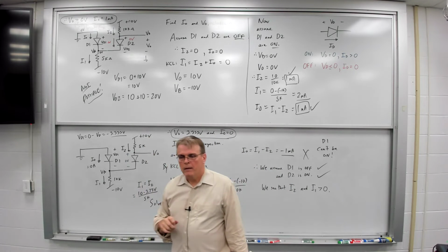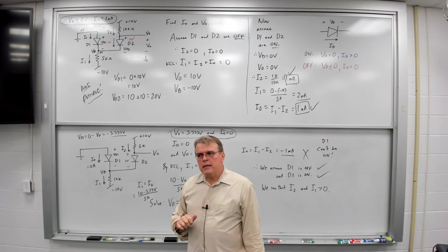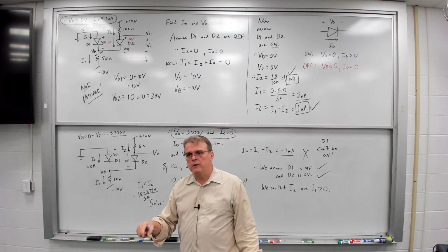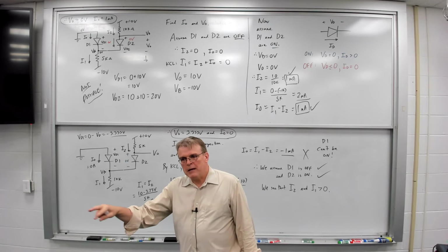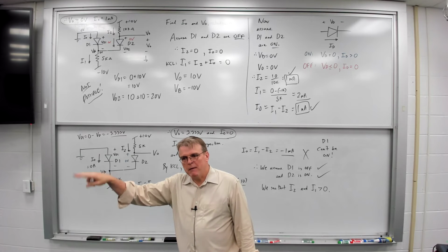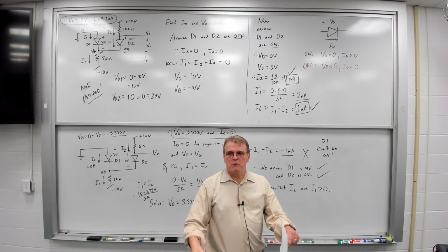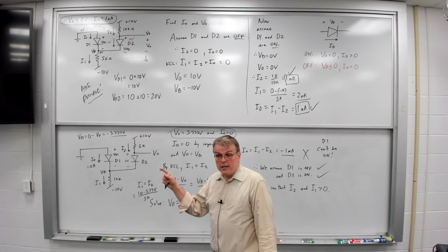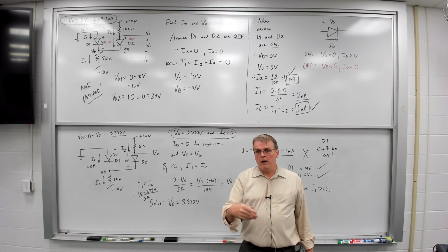Yeah. But isn't that property unique to logic circuits? Well, it's not unique to logic circuits. You can see it in comparator circuits, for example. You can have positive feedback in a comparator, and you can actually have a bistable state. If you took Circuits 2, you built a bistable multivibrator that basically flipped back and forth and created a square wave. Remember that? That was a circuit that was literally flipping its own state back and forth using positive feedback. So it's definitely possible to do that, but we're not going to be normally covering this. That's, once again, kind of beyond the scope of this course.